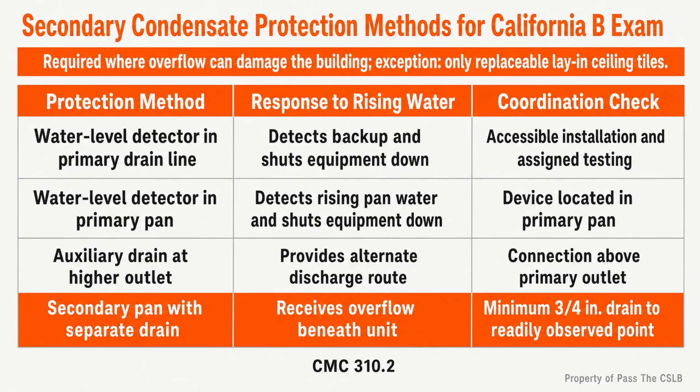Attic condensate protection cannot be separated from attic service access. A beautiful drain installation is not inspection ready if the equipment cannot be reached, removed, illuminated, and serviced from a stable surface. These requirements need framing and electrical decisions long before final mechanical startup.